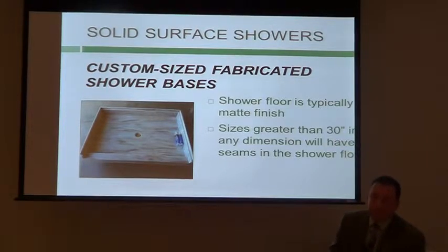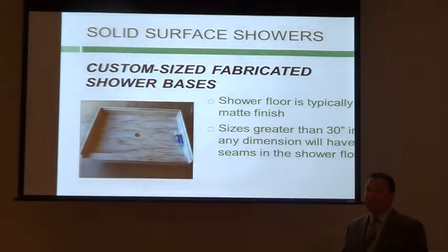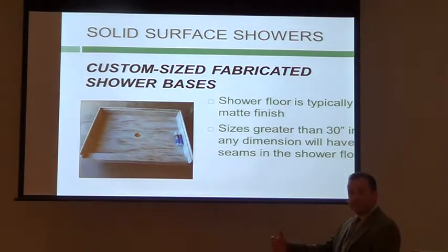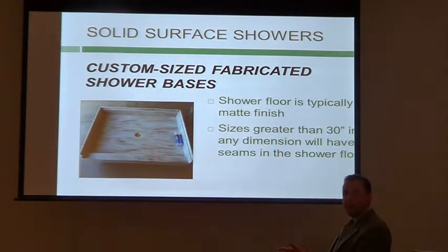So every manufacturer standardizes around a 30-inch wide sheet. Well, in a commercial setting, when was the last time you saw a 30-inch wide shower? They don't exist. ADA compliance at minimum is 36 inches finish wall to finish wall. Most of the time, it's going to be 36 inches deep and either 4 feet wide or 5 feet wide. Pretty common. So a fabricator to meet that need has to glue some sheets together.